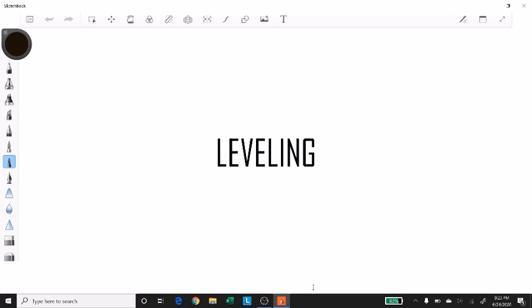So in leveling, basically what we do is we either try to create vertical control over an area, or we might try to execute a project by carrying out a layout survey. So it could go either way, but what I mean by gaining vertical control or laying out points is that in the vertical plane you need to find out relative height of points. That means I need to find out vertical distance between different points, or elevation difference between different points. So that is called leveling.